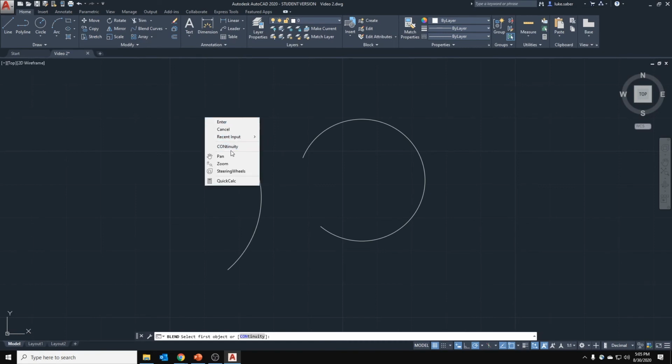The options involved are continuity. Now it says tangent and smooth. I don't know why those names are like that, but the biggest difference is, if you remember how you can make spline lines, you make spline lines by clicking a bunch of separated points and using those as reference to make a curve around them in a weird way. Well, basically tangent just has 3 reference points and smooth has 5, and I'll show you the difference because I'll do one at the top and bottom.